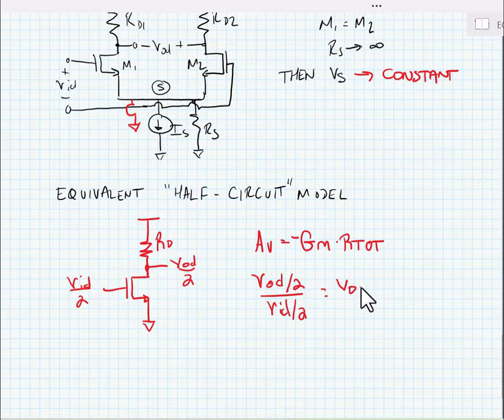And we know the voltage gain for this simple circuit is equal to minus little gm, and R total is approximately equal to RD. Of course, if we wanted to be more exact, we could note that the transistor also has some output resistance.